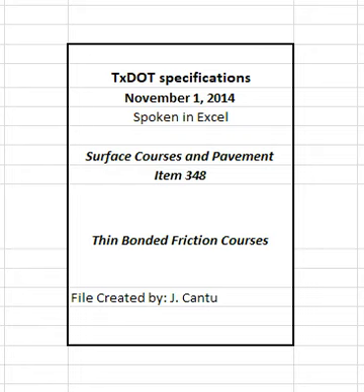4.4.2.1.4 Submitting JMF1. Furnish a mix design report, JMF1, including Hamburg and overlay results. Provide representative samples of all component materials and request approval to produce the trial batch. 4.4.2.1.5 Supplying aggregates. Provide approximately 40 pounds of each aggregate stockpile unless otherwise directed. 4.4.2.1.6 Supplying asphalt. Provide at least 1 gal of the asphalt material and sufficient quantities of any additives proposed for use.